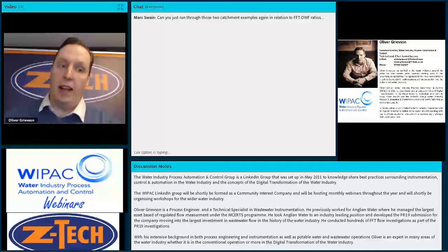There's some technical issues. I spoke about Bulletin 27 earlier, talking about large measurement distances. I think in the end with Bulletin 27 we got to the right point and agreed: have we got a fully developed flow profile? There's going to be some more work on this, and some of the water companies are leading on that work, which is great. And we'll get to the bottom of area velocity, and it's a great piece of work. But what's next? The certification of storm duration monitors and the standards they're going to have to conform to.